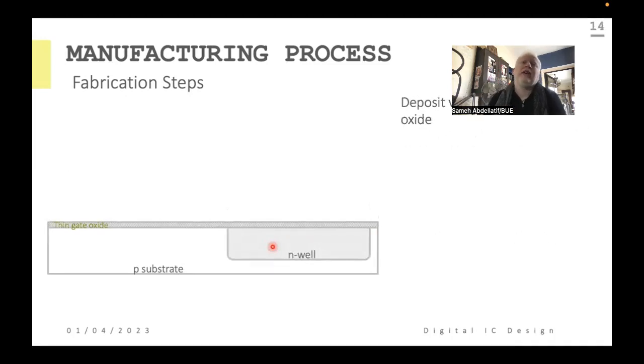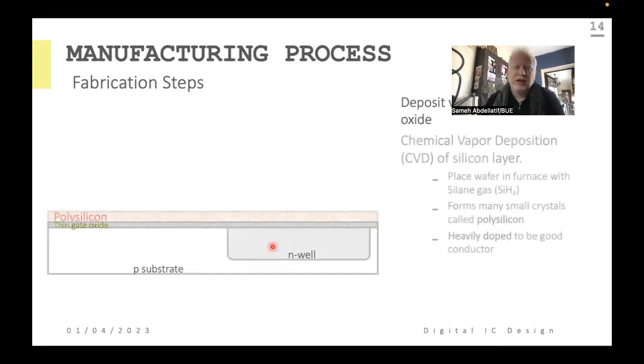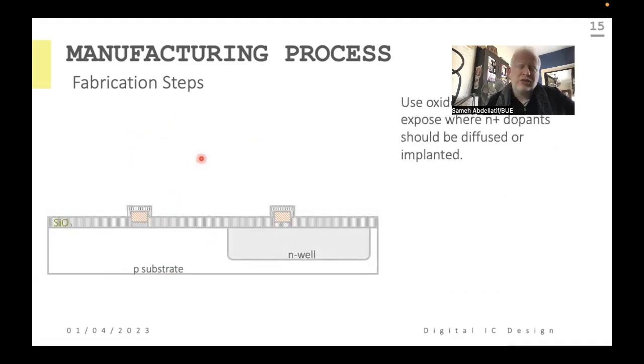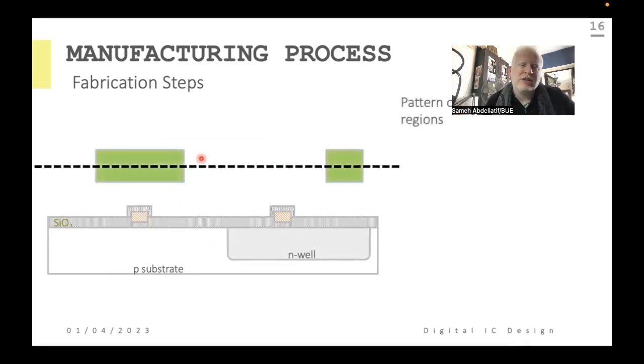And I think we already discussed a lot before about the importance or the impact of this gate oxide, in what we can call the oxide parasitic capacitance in a MOSFET. So after that, we can start having the position for the two gates. The one on the right is the gate for the P-channel MOSFET, while the one on the left is the gate for the N-channel MOSFET. Then we insert another passivation or oxidation layer. And then we start the doping process with our two kinds of doping.